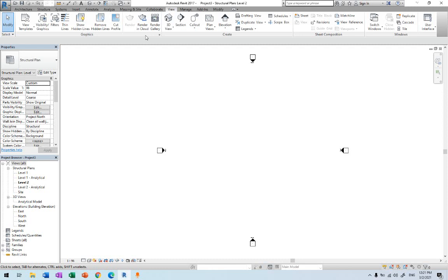For example, let's say that I'm in Magosa, I'm building a house, I know the exact location. I can give that location to Revit. Revit will show me the direction of the sun and which room it will hit, because of the light analysis. They have this feature, which is lovely, and architects love this feature. By providing a real shadow, real sun analysis, it shows how the sun is rising and going down, basically hitting which side, which windows. That will be out of our scope, but just to know it, if someone is interested, they can go for those things as well.